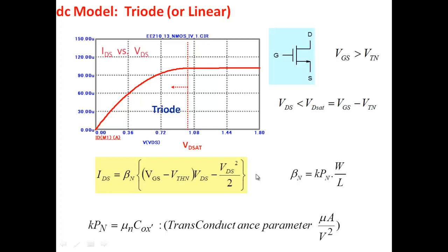And interestingly, so we are neglecting it, we are looking at it here. So MOSFET is a resistor, but note the value of the resistor you can control by controlling the gate voltage here. Depending on how much gate to source voltage I apply, I'll get different values of resistance here. So MOSFET in this particular region, what can I call it, a voltage controlled resistor.